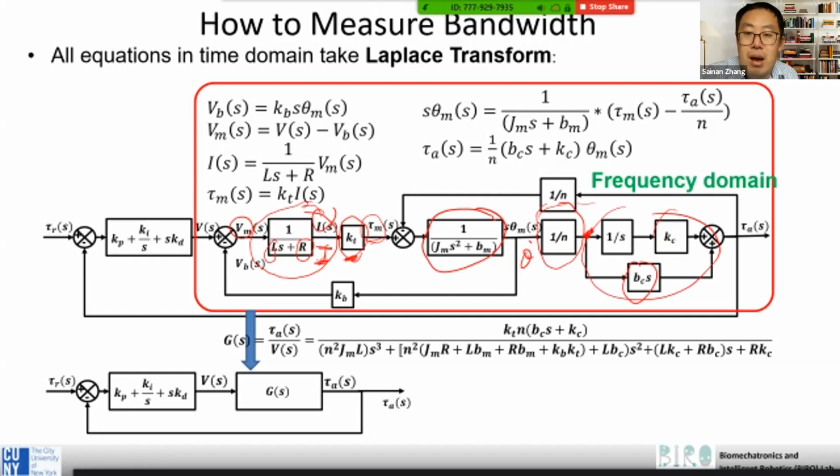So this is the gear amplification. In this case, KC, you can think of this as the series elastic actuator, and we get some kind of stiffness, right? In a load cell, you can think about it like the SEA. We use a spring at the load cell. We can measure the torque, right? So that's why you get this torque here.